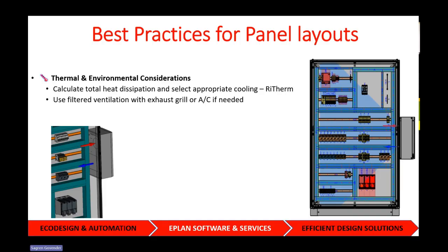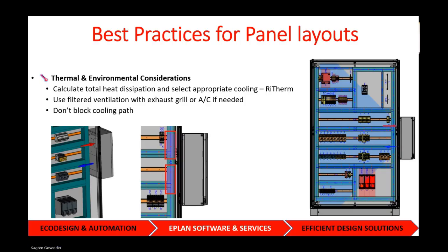It's best, if you're using a fan, to have it filtered and make sure you have an exhaust grill to match that fan. And again, if you look at Rittal, it has some cool products around the fan, some self-cleaning filter fans, so have a look at that as well, and that could help you. And again, based on your calculations, you may need an aircon unit. So have a look at that.